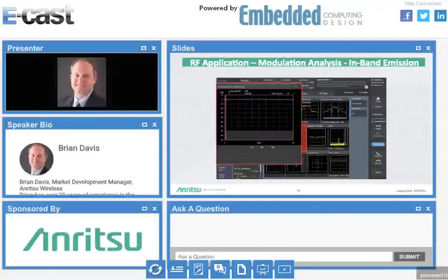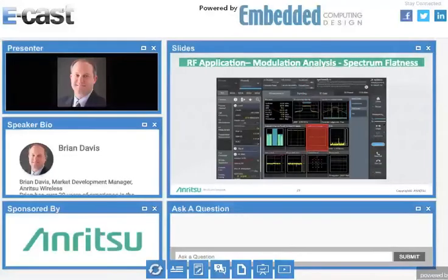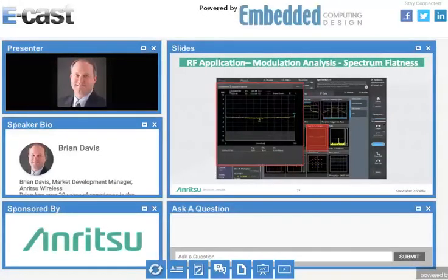In-band emissions, this is the resource block power spectrum for the data specified by the measurement interval and the measurement offset. So you have markers there that can go into more detail. This is across, looks like 50 resource blocks there. Spectrum flatness for uplink, this is to calculate the limit lines.